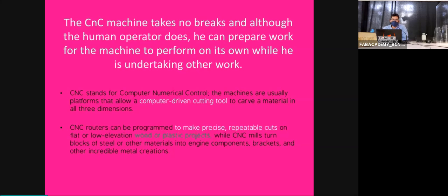So they just ask if it's safe when, for example, you are cutting metal with a machine and it produces sparks. Usually, you should not produce sparks. Sometimes pieces of material can ignite. It doesn't need to be metal. I have seen wood catch fire. I have seen a machine on fire, a full machine. This is because of bad settings of the machine on the cut. It's something that you should always avoid. There are mechanisms to reduce that risk when cutting high strength materials. But if you are cutting properly, you should not get sparks of any kind.